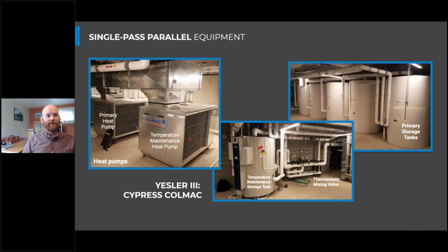And even though this is essentially the same product, we can configure that cycle in the single pass heat pump water heater or the single pass cycle to treat our primary load and the multi-pass to treat our temperature maintenance. And we have our primary storage tank. This is where we're storing that hot water.